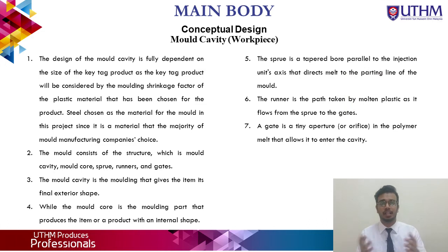Moving on to the next, which is the mold cavity of a workpiece. So the design of the mold cavity is fully dependent on the size of the key tag product, as the key tag product will be considered by using the molding shrinking factor of the plastic material that has been chosen for the project.